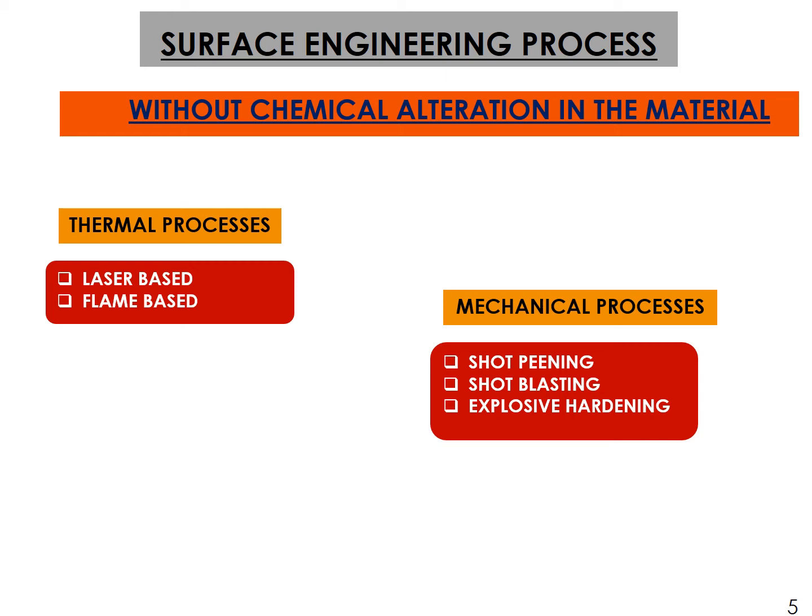In the shot blasting process, again, as we're discussing, these are surface treatment processes. So in shot blasting, what we do is we throw high velocity abrasives onto the surface. With the high velocity abrasives, the surface is cleaned and is ready for the secondary operations.